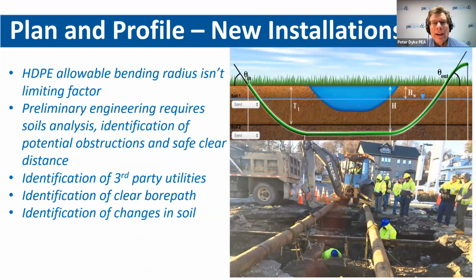Generally, Alan, how I answer that question is: absolutely, it depends on the region, it depends on the market and how mature the contractors are. But before COVID, polyethylene was about 10% more expensive than PVC off the shelf. Now we're less expensive than PVC off the shelf. And with trenchless, 90% of all trenchless jobs are polyethylene. So trenchless is typically 40 to 60% the cost of open cut. But once again, projects vary, so it's a difficult question to answer with certainty.